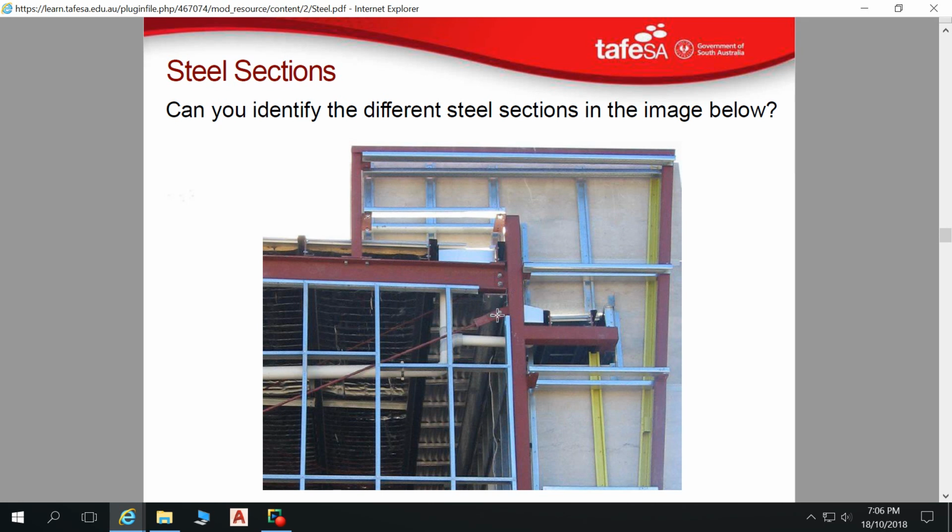Here, we've got a flat plate cleat, going to another cleat with our bracing, which is our rod, so it's a steel rod. Then up here, we've got SHS once again, this one SHS or RHS, I don't know whether that's rectangular or square. So that's pretty much it for our hot rolled sections. But then we've got a whole heap of cold rolled sections filling in the next part. Our hot rolled has been painted in rust inhibitor. These ones have got a zinc aluminum coating to them.